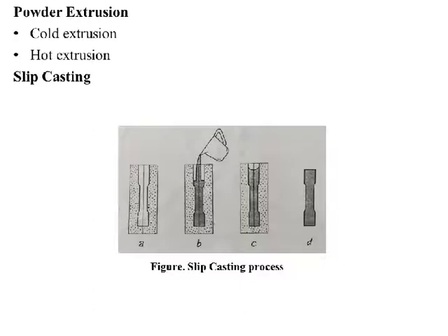So these binders that are added during the cold extrusion process have to be removed during sintering. Okay, so this is in the case of cold extrusion. Whereas hot extrusion of powders is usually carried out by a canning process, wherein the powders are evacuated and sealed at the end. So that is hot extrusion.